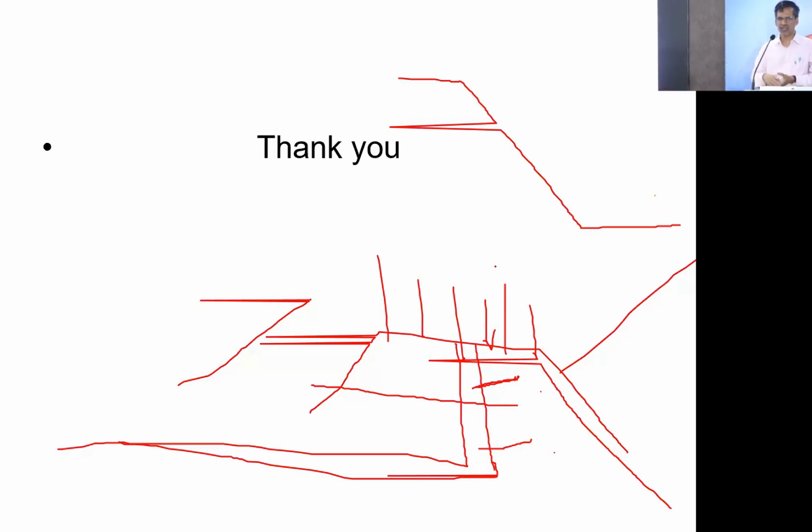But how do they anchor it to the soil? We just excavate a 1 meter depth trench at the top of the dike, put the liner in, and load it with soil at the top of the dike.